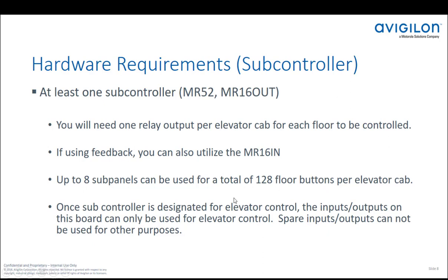One final note: once a subcontroller is designated for elevator access control, the inputs and outputs on that board can only be used for elevator control. You cannot use those spare inputs and outputs for any other functions.